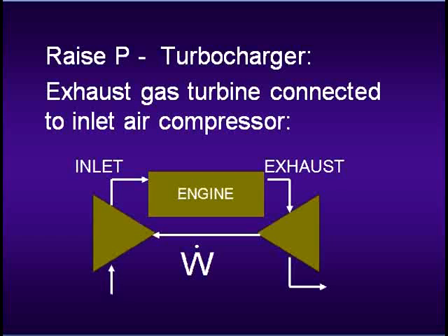One of these is what's called a turbocharger. What you'll do is take the exhaust gas as it comes out of the cylinder. It's slightly elevated in pressure. We'll run that through a turbine, take the shaft of that turbine and run a compressor so that we bring intake air in and compress it, and now you have a slightly higher pressure coming into your engine, and that'll allow for more air to be stuffed into the cylinder.